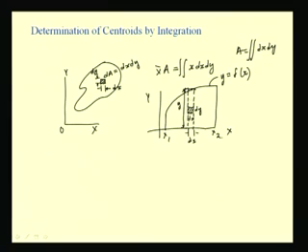So, now the double integral has been converted to a single integral, where if I consider these elements, I know that the centroid of this rectangular strip will lie here, which I may call y bar of the element. Now I can sum these quantities to find the centroid of the area under this curve.